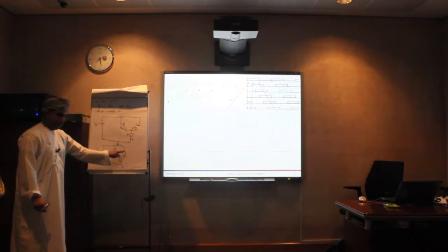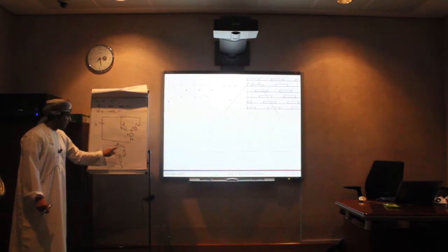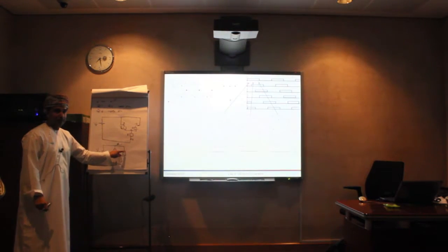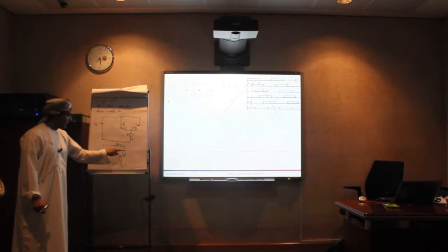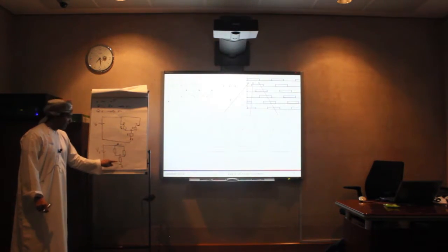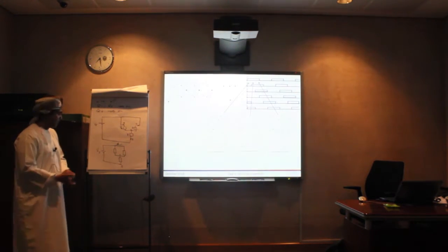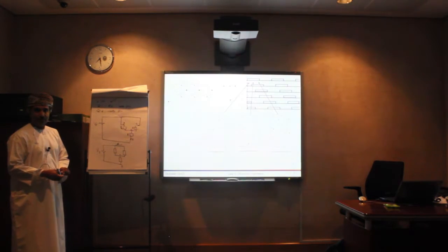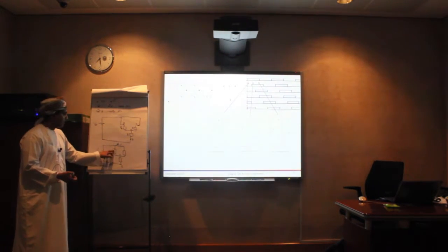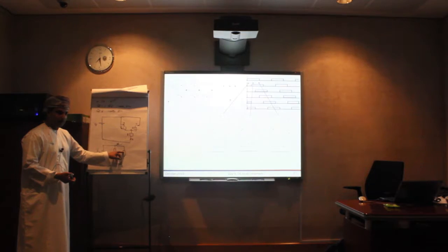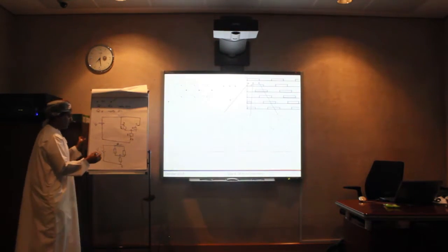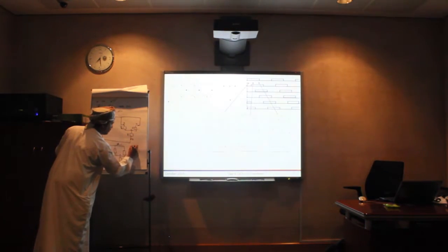This is those two in parallel, right? So R1 by R2 over... that means it's R over 2, right? And this one R. So the total of the resistance is 0.5 R, which is R over 2, plus R. So the total is 1.5 R.